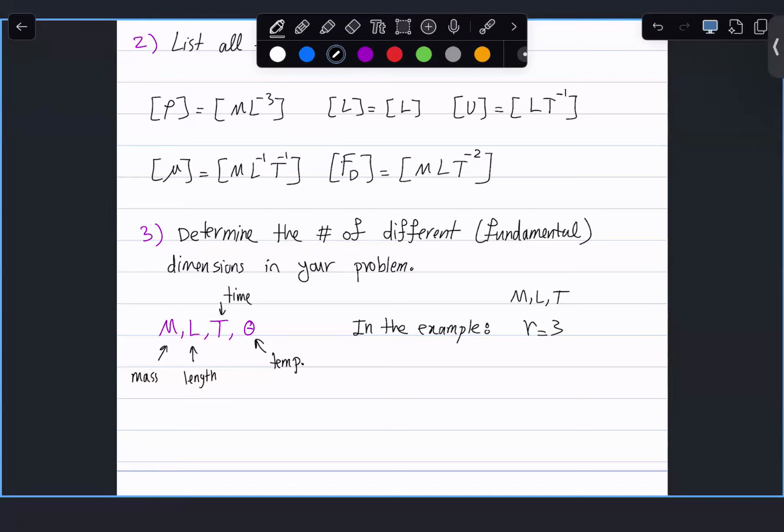Yeah. If you get the inverse of rho UL over mu, that's fine. It's still dimensionless, right? You can flip them, you can multiply by a constant, still dimensionless. But they usually write it as rho UL over mu because that's called the Reynolds number. It's very famous. You'll get mu over rho UL. Yes.